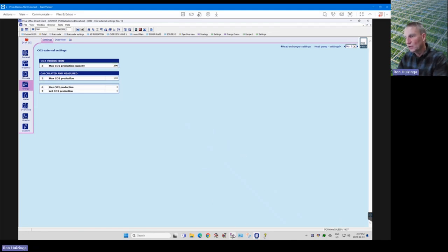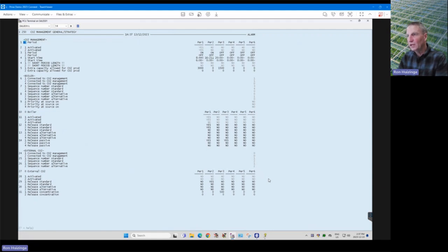And basically on this page, that's what many customers are doing. They're saying during the day, I know my buffer tank is going to fill up by the end of the day, so I don't want to use my liquid CO2 during the beginning of the day. In the afternoon, if my ppm drops below 450 or so, then I'm going to allow my liquid valves to go on. And only for the peak of the day, so you make some time periods up here.